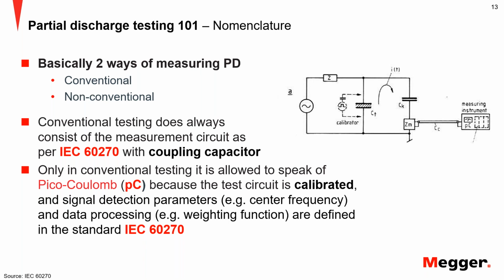So you're only doing an IEC compliant test if you do the full program that is covered under this term conventional PD testing. Anything else is non-conventional.